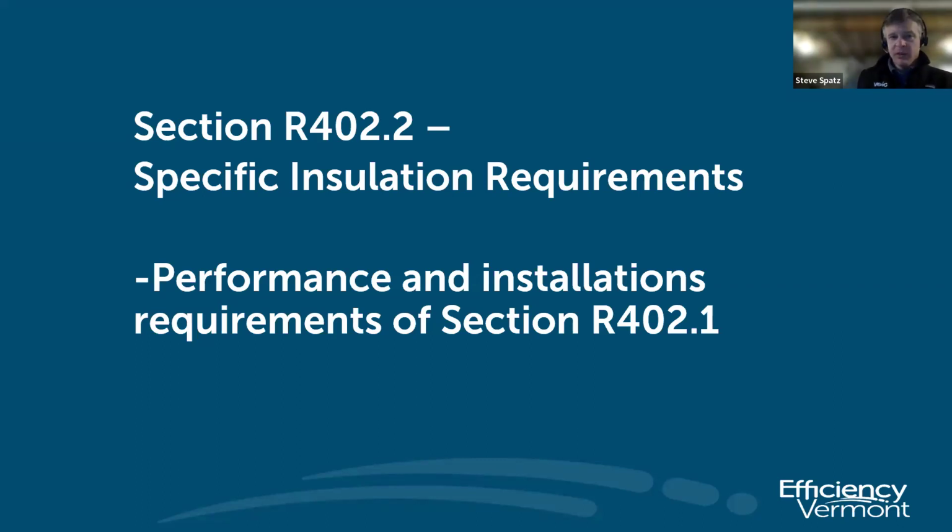So as I noted at the beginning of this, those are the prescriptive requirements for the different building envelope components. That is what is defined in the table and your package option. But beyond that, as you start to go into the points options, you expand beyond the building envelope components and get into mechanical equipment, air leakage, water use, et cetera, heating and cooling equipment. So the scope goes beyond the building envelope as far as ways to be increasing the efficiency of the home and earning points.